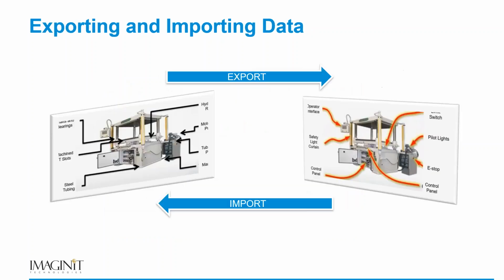Now, this has been around for a while, where in the past, we could link these together really with an import-export. Typically, we would export things from AutoCAD Electrical and import them into Inventor. So we could export, for example, a wire list from AutoCAD Electrical and import that wire list into Inventor, so that we understand how these components wire together. It's been around for a while. I can't even remember which release that came out in, but it's been out for a good while.